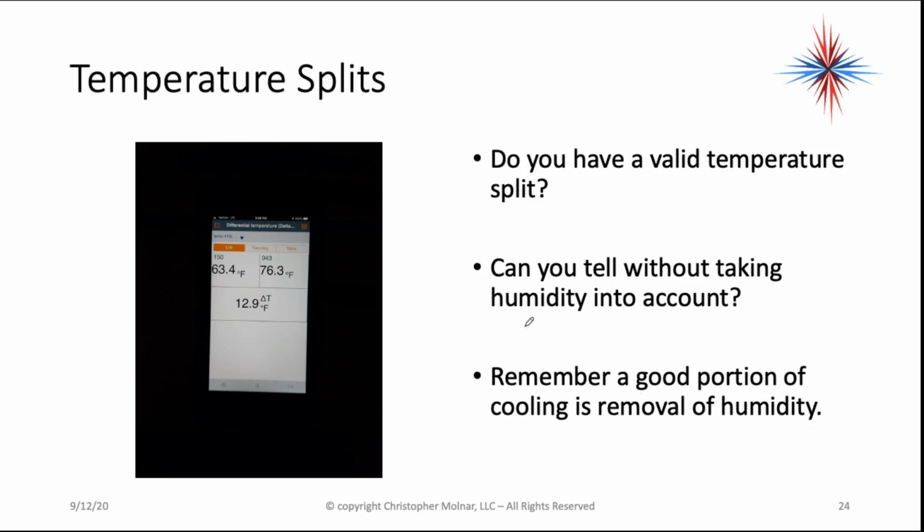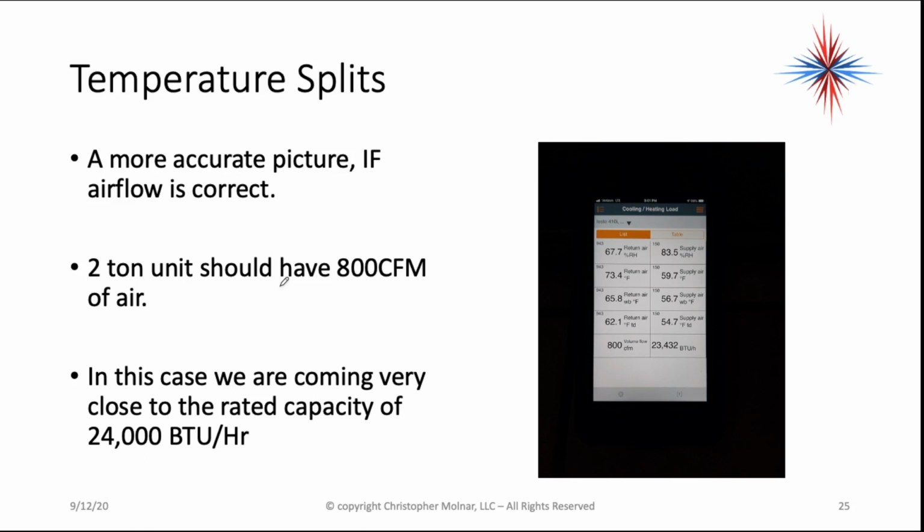Remember, a good portion of cooling is the removal of humidity. So without taking wet and dry bulb, is this right? Is this wrong? You really can't tell. So we have to look at a more accurate method. Okay, this is, again, using the same temperature probes that I already had in there because they do wet bulb